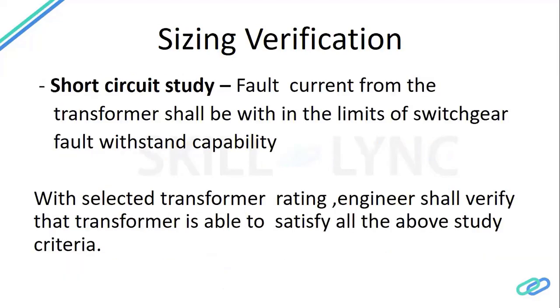Third is the short circuit study. Short circuit study means the fault current calculation, because as I told you in the MVA current limitation slide, you will check what fault current is supplied by the transformer in case of fault. So we will simulate the fault in our system, and we will check how much fault current the transformer is supplying. If it is within our limits, we can see, okay, our transformer is okay.